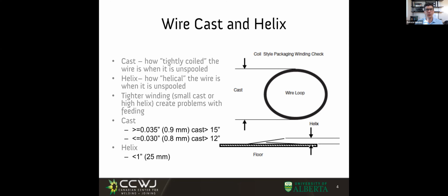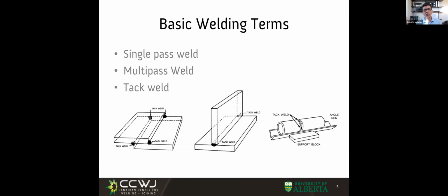But if we have many passes, then interesting things happen. It doesn't seem like that much, but for example, in a single pass weld, if the plate was a little bit dirty, I can put some magic spice in my electrode that will clean up this dirt, right? That can be silicon or can be manganese. We will discuss all this later in the metallurgy section.